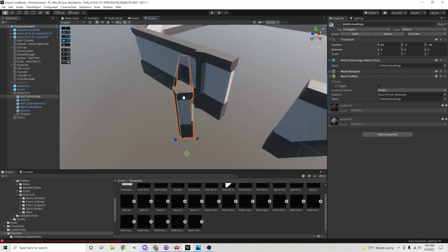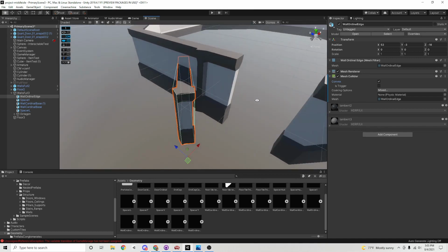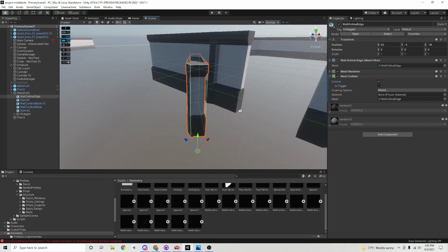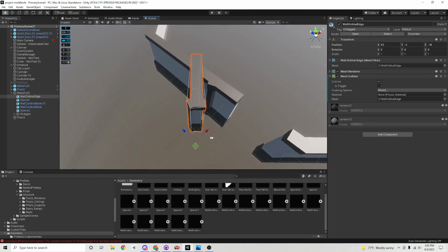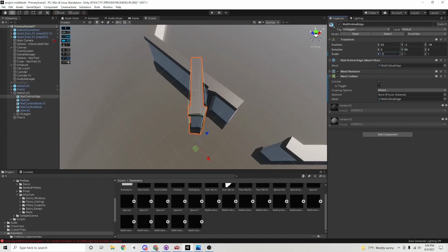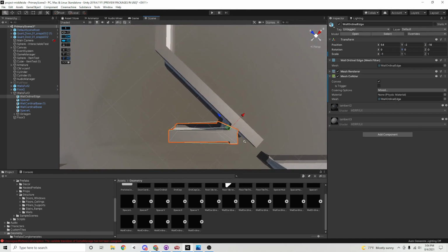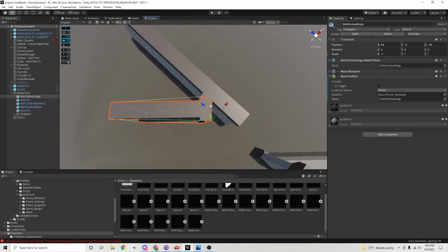And in case you're curious, I'm clicking convex because it makes the collider calculations in the engine a lot easier when the game is actually running, and it's perfectly fine for all of the walls to be convex. The only ones it's not fine for are the door pieces, which we will go over in a moment. Move them over here, and let's rotate 90 degrees and scale by -1. Rotate by -90 degrees. Rotate by 0. And I guess that works. There we go. Now we've got a cardinal wall piece.